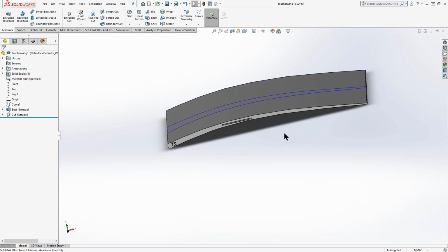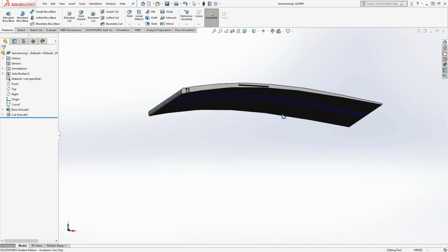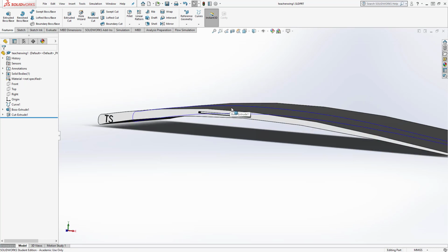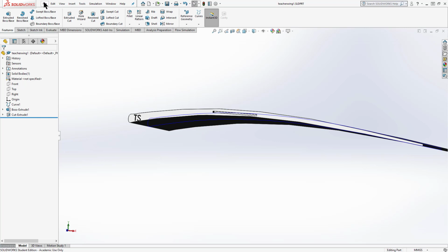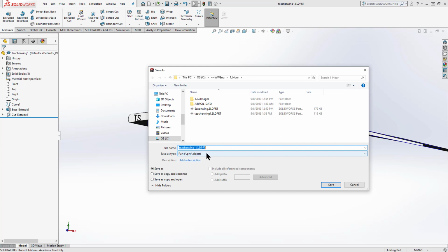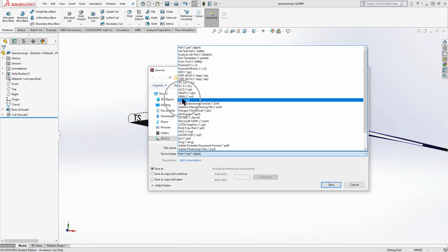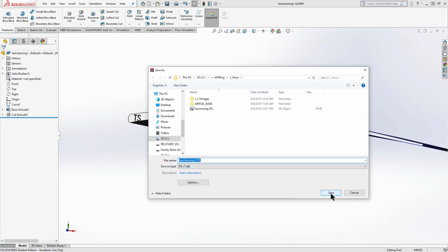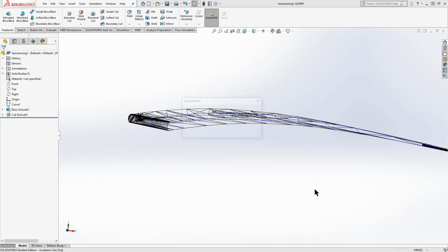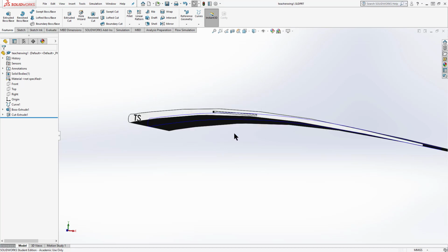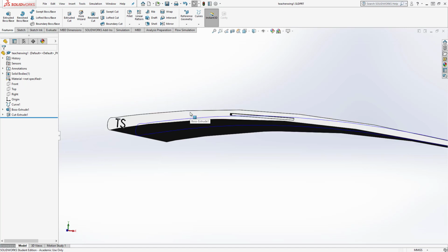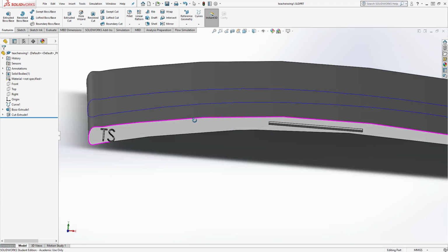And now the next thing I want to do, I'll submit that part file because this allows me to open up your part and be sure it will work right and it's sized right. The next thing I'm going to do is save it also so I can 3D print it later. This time I'm going to give it the same name, but I'm going to make it a .stl file. And we'll learn more about that in our next module, about how we 3D print them. It asks me how many triangles, and just go yes. You may get asked whether it should include all bodies, and the answer there would be yes. And that just means you've got something disjointed a little bit in the print.